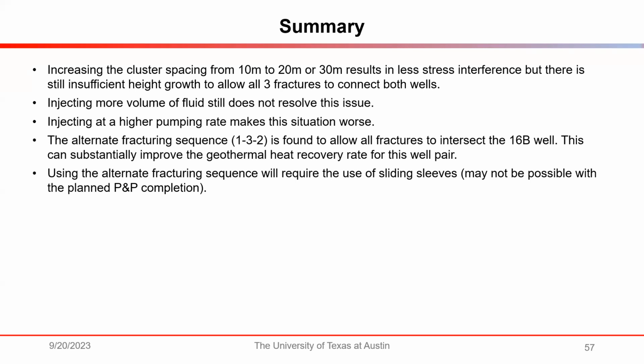And so what we do is we literally just take the aperture, multiply it by a factor, like just multiply it by 0.5, and then put it in the cubic law. So you made the conductivity during propagation 8 times lower. And if you do something like that, you get less irregular shapes, still irregular, but less irregular. And I actually had to do that as part of the match to the stage 3 geometry.